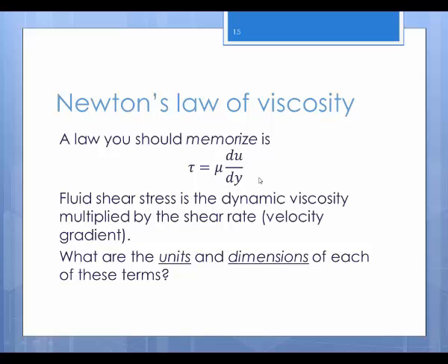Newton's law of viscosity is really important. It basically says that there's a shear stress. Remember, shear stress is just the force per area. So it's the fluids sliding past each other, those parallel movements. So there's a force per area that represents resistance to flow, and it is the absolute or dynamic viscosity times the shear rate.